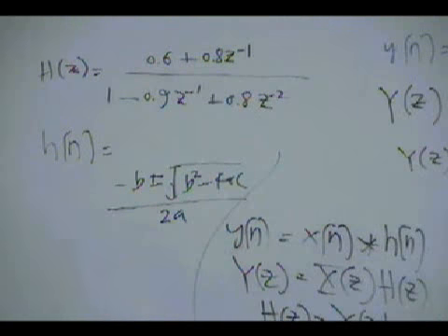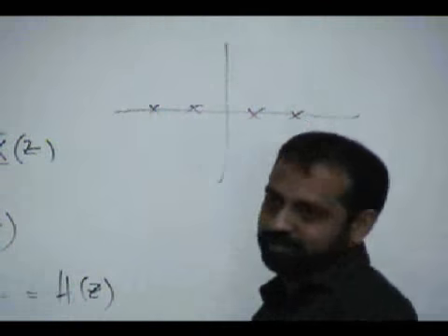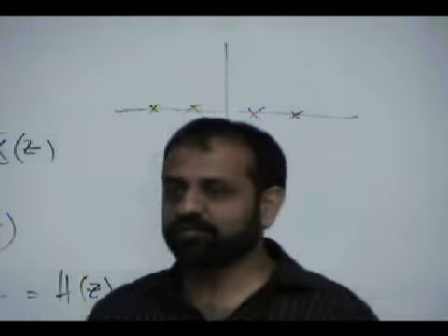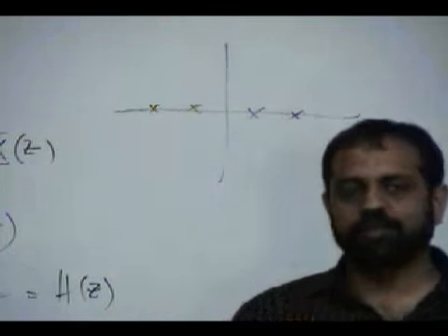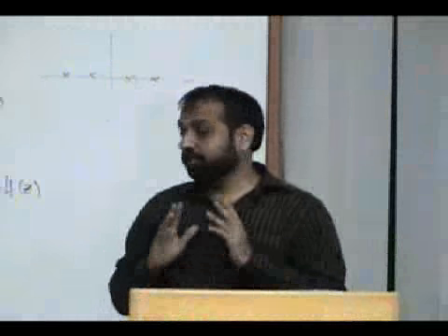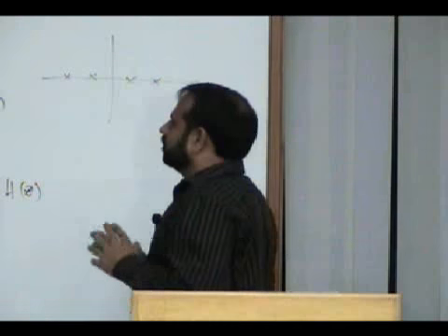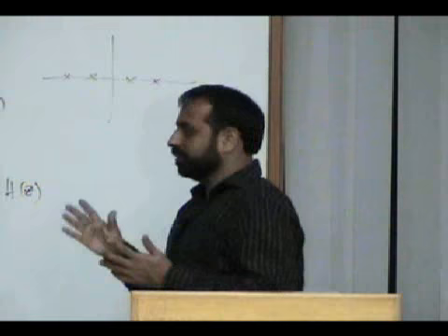What is meant by real poles? Real poles mean that poles will be on this line. They may be anywhere on this line. Okay, these are real poles. We'll see the significance of these poles, but that is the whole story. Now, you design a system, you plot the poles, and you also plot the zeros. If the poles are real, they are on this axis.